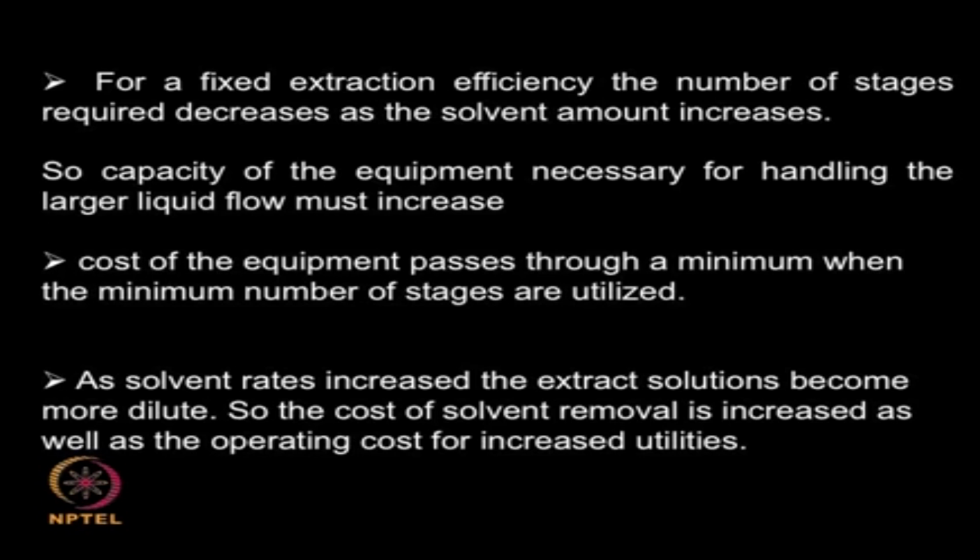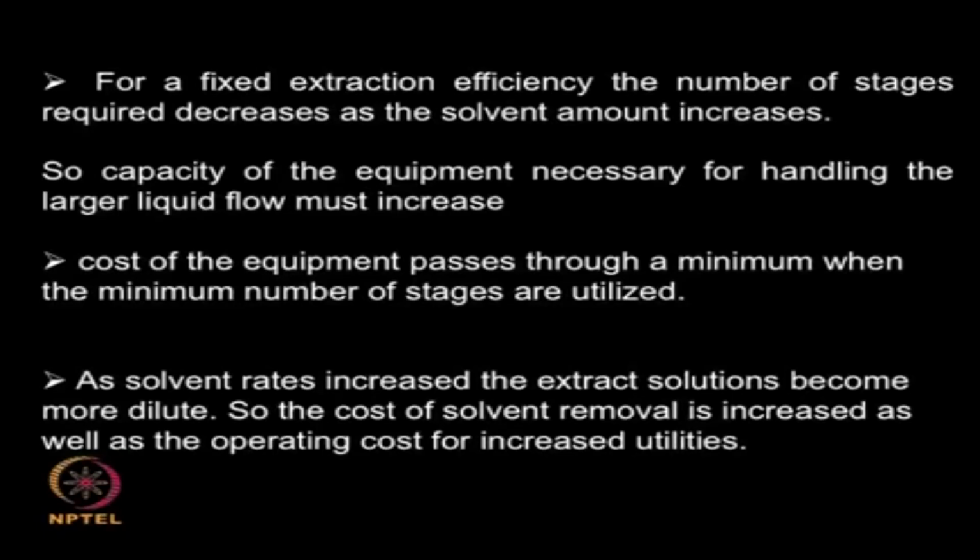But if I have fewer stages and more solvent, obviously the size of the stage has to be sufficient for handling so much liquid. So, each stage may be of very big size. You see, the advantage of reducing the number of stages is balanced by an increase in the size of the stage. When I have a larger sized stage, the cost increases, but I may have fewer stages. So, you need to find out which is more efficient.